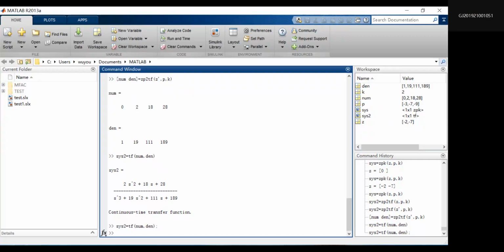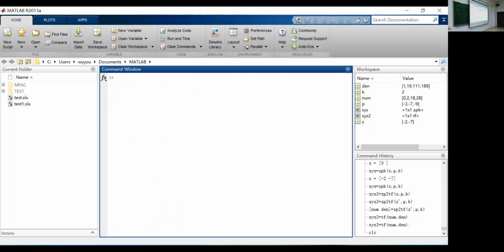First, of course, you should type in these two systems into Matlab. How to type in G1? Start with the numerator, we name it num1. What is the numerator for the first G1? 1 and 2, right?